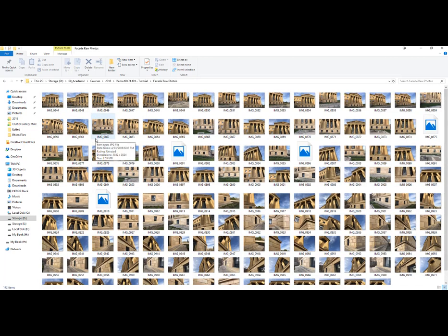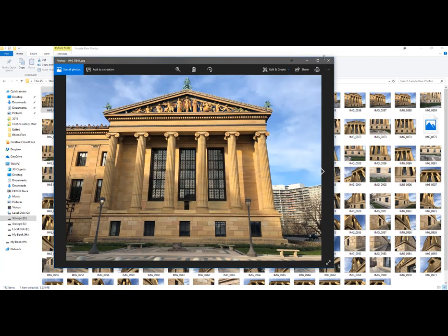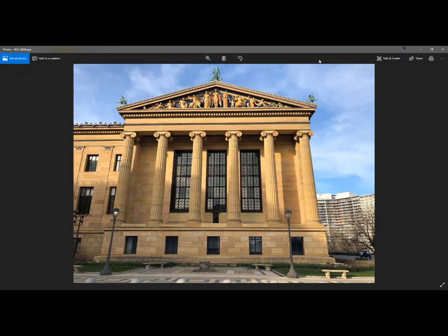There's a few rules that we need to follow when taking photographs. One is to never zoom. By zooming in and out with your camera, you change the metadata, and ultimately the photogrammetry software will have a hard time understanding where things are. The second rule is to take all of the photos at the same time of day. You can take several photos from a similar camera at the same site and stitch them together, but if we take some photos in the morning and some photos at night, it's going to be hard for the software to recognize what's exactly the same and match things up.